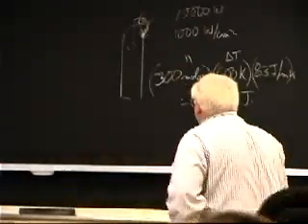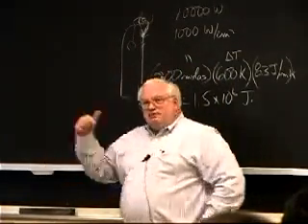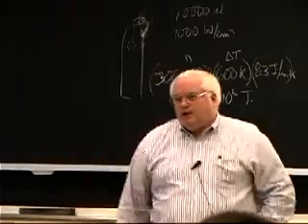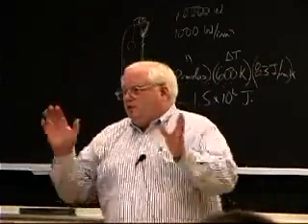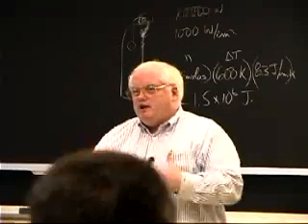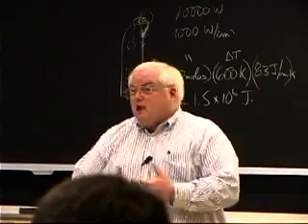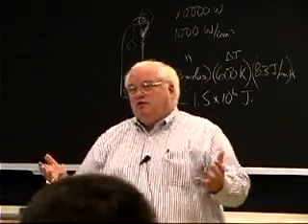You can also show it's bogus because this is a 1/4 inch thick wall, and you can estimate how long it takes for the heat to penetrate the wall. Turns out it's about 10 seconds. We'll learn that later in the course, how to estimate that. The point is, you actually can estimate these things. You can put numbers on things, and you can tell the difference between 2 theories in a failure analysis.